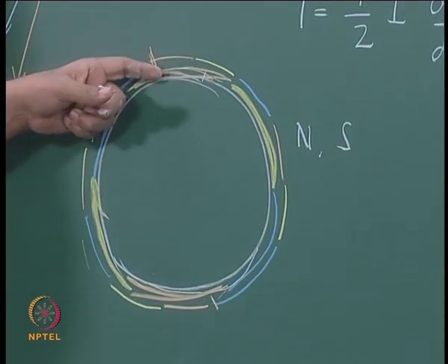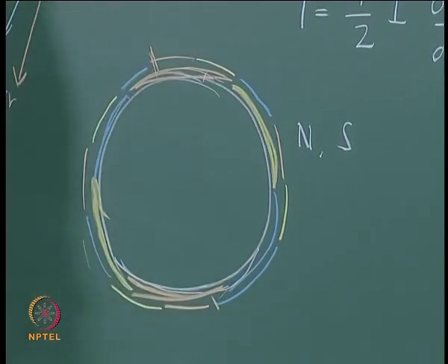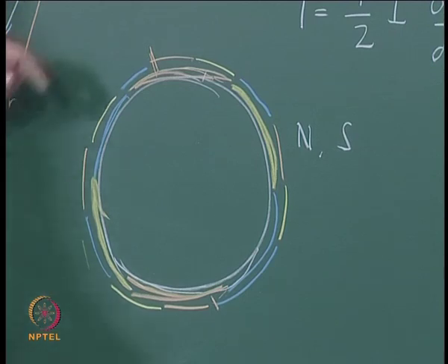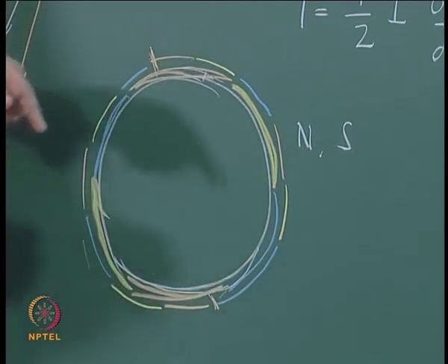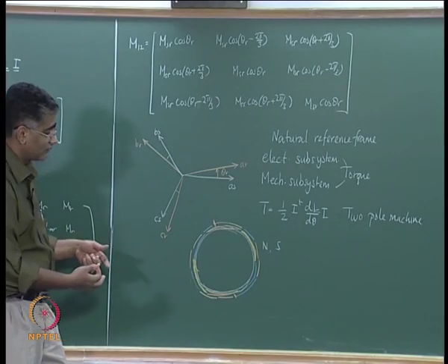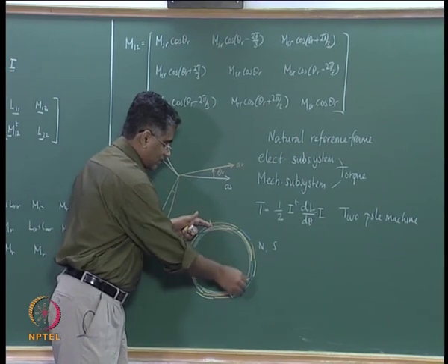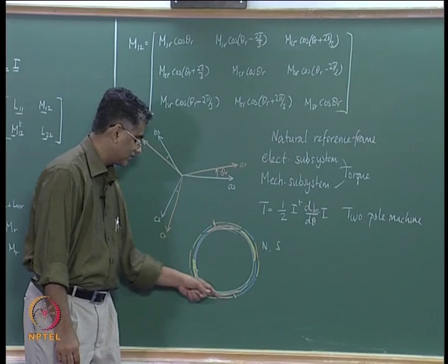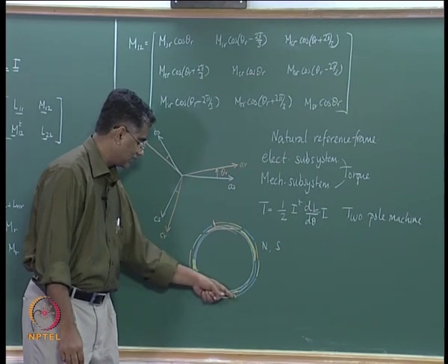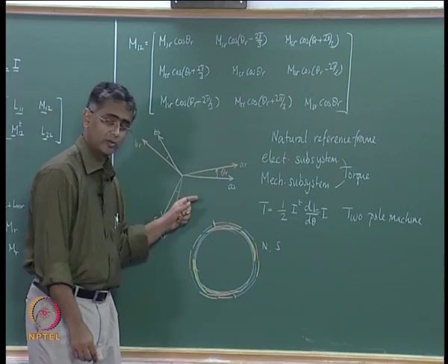There is no difference between what the machine is going to see here and what the machine is going to see here. Therefore, it may be sufficient if you analyze what is going to happen here, which means that it is enough if you analyze one cycle of the MMF waveform. It is not necessary to look at the other similar repeats of the MMF waveform.